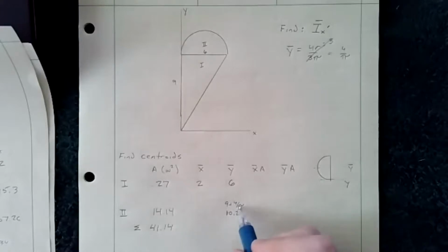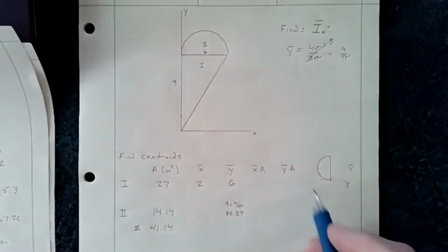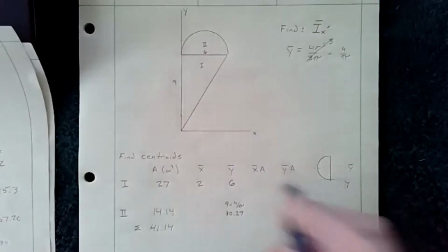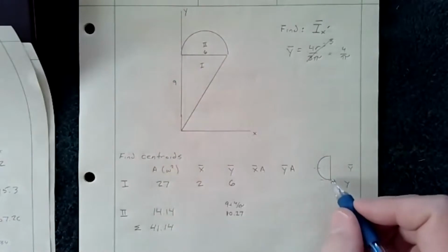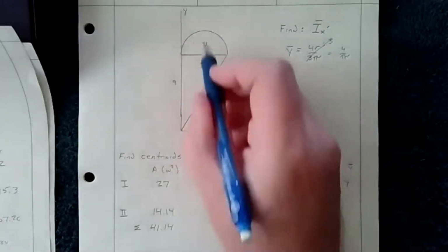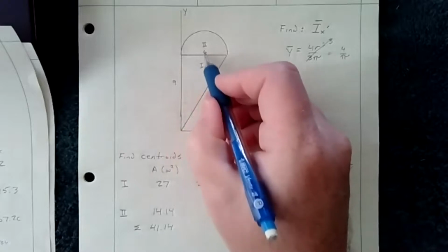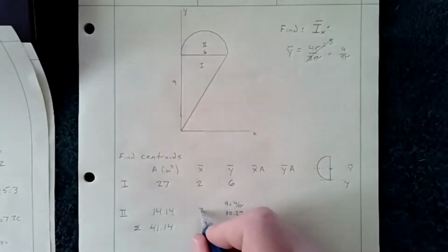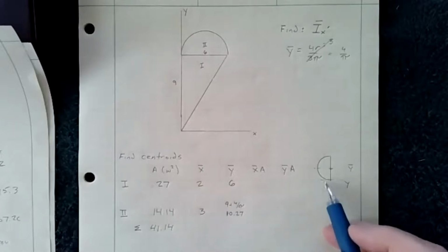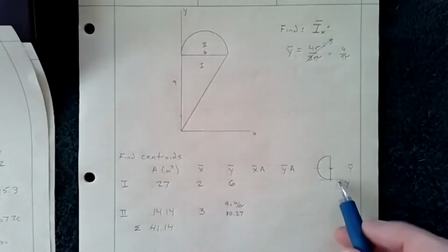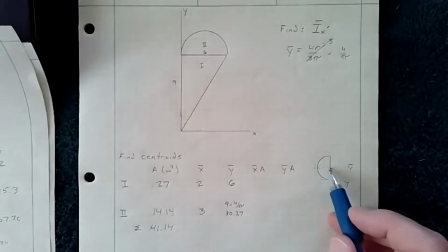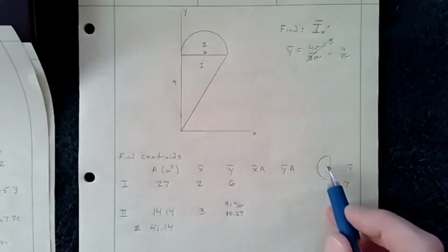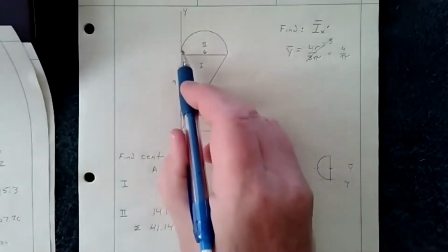X bar, if I look at a circle like this, from the orientation of X bar, it kind of looks like this. It's just going halfway. So if I just go this far in, it's just going to be 3. So X bar is just 3. I drew this just to illustrate that this has to be the center of it because it's halfway through the circle, meaning there's just as much material above and below. Same way if you come from this direction, okay?